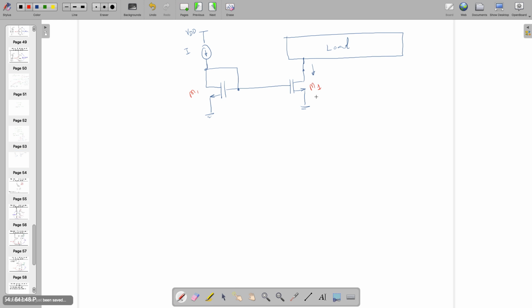And we also understood that if a current source is given to you, you have to evaluate whether it's good or bad. There are only two parameters which we need to see. First, the source impedance has to be infinity and the minimum voltage has to be 0. So we know that that can be done by the simplest technique, which is cascoding the transistor, or cascoding the stage. By doing this, we also agree that here it's Von plus VTH. That's why this is only Von.